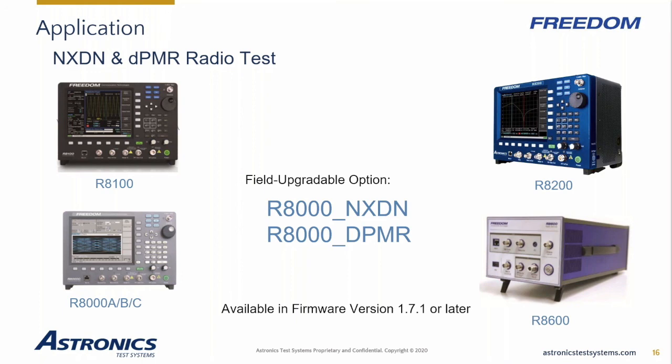But the main thing that I want to share with you here is that, for example, the 8200, which is a brand new unit, is going to come with a built-in single port VNA, so you're going to be able to do more accurate measurements when it comes to VSWR, distance to faults, and also you're going to be able to do Smith charts with this unit. So instead of carrying different units to the field, you just have to take one with you, and you'll be able to test radios and do all the maintenance in the field for all your passive components in the network.